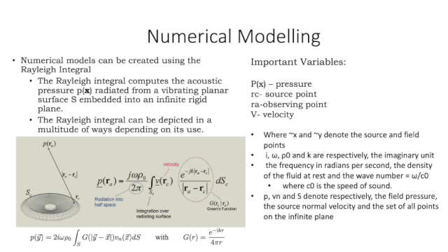The numerical models that will and have been utilized for the modeling are created using the Rayleigh integral. The Rayleigh integral accurately predicts the acoustic pressure radiated from specific planar surfaces, which tend to be small individual elements on the focused ultrasound transducer. The equations are given below.